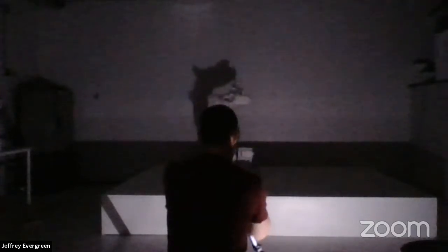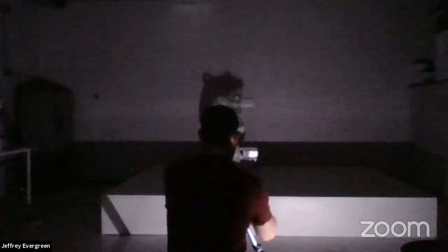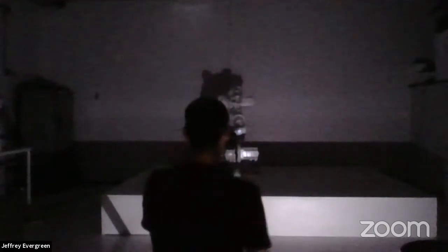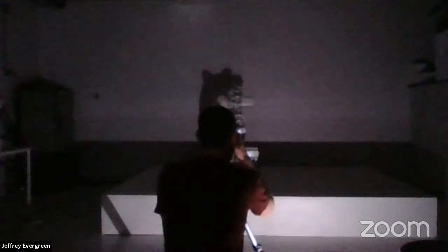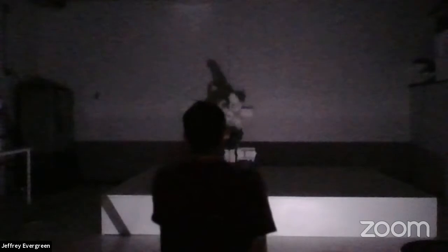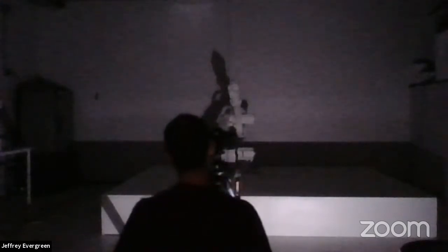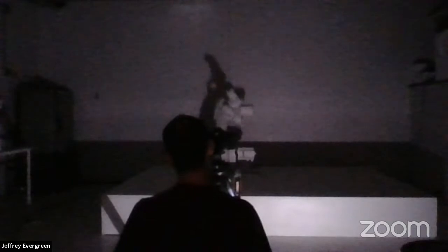Let me just pull up the file super quickly. I think is it related to what you showed earlier, the little twig that does the drill to get to the first point? Because in the file you're going directly to point 0, right? Straight down instead of doing that. I believe that is automatically generated by PowerMill. Not necessarily, but oh, you mean if we were to add this to our Rhino file, we would have to add it, or at least script it, saying you enter at an angle and then start following the toolpath.